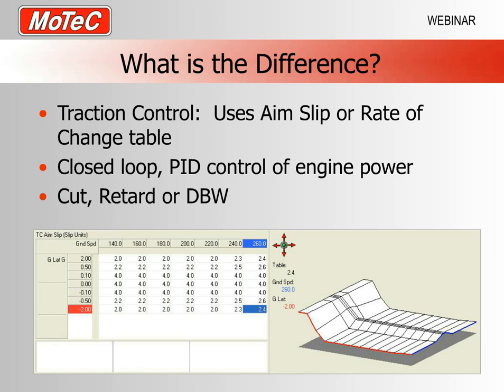So what I've done here is my table, just for a bit of an explanation of how intricate they can get these days, is we have a ground speed along the top. So as ground speed changes, if you look at the numbers, we change the amount of slip that's available. And I also have a lateral g-force. This being a circuit car, a tyre can only give its maximum grip in a certain direction. So if you're going in a straight line, you can put all of its grip into going in a straight line.